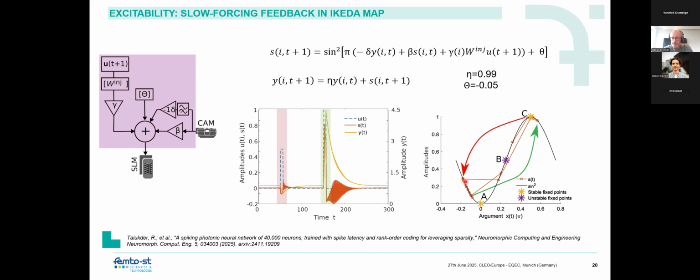And what happens here is we can look at the stability diagram. Let's say we sit our system at this point, choosing the bias offset here. That's the rest point of the system without any input. We now drive the system with an input, and we see here the stable fixed point and the unstable fixed point. As soon as this drive crosses the unstable fixed point, the system gets projected towards the upper stable fixed point, and this would normally be bistability, because then the system would just do its stuff around the attraction basin of point C. And this is where this negative high-pass feedback forcing comes in.